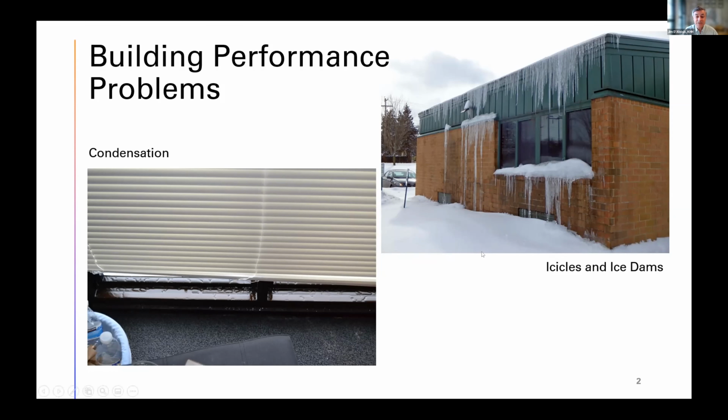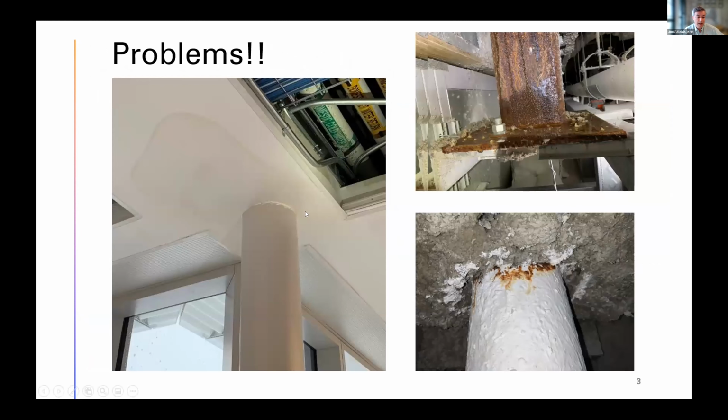You got ice dams and icicles. It might be that roof to wall connection intersection where the spandrel beam has some bad steel continuous thermal bridging things going on. It could be air gaps too. It could be a combination, but I've learned firsthand minimizing problems in buildings that I see as a forensic engineer, as well as design engineer. These aren't my projects. I want to say that. These are my forensic investigation projects.